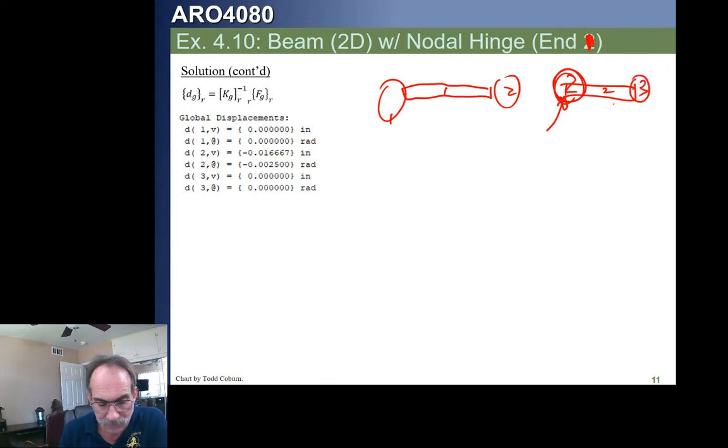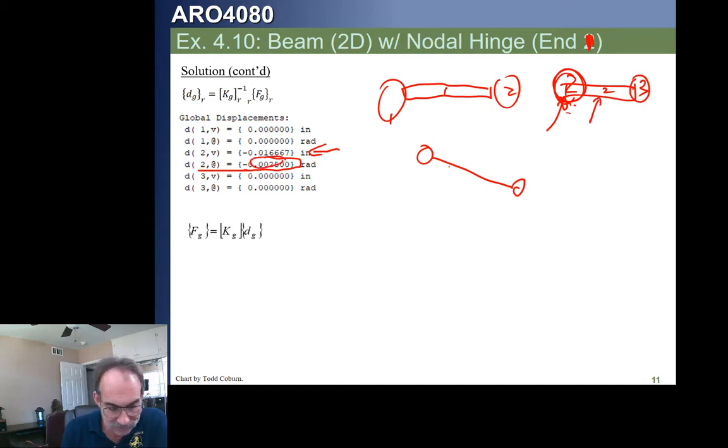And we actually have the hinge noted here on this end, which is node 2 of the second bar. See that? Okay, since it's in this one, you'll notice that this rotation that we get, or this displacement, is the displacement of both nodes. So you'll see this guy going like this. Since this is the one we modeled in element 2, that means this applies to element 1, and you can see that it's a negative slope there, right?